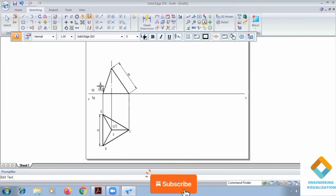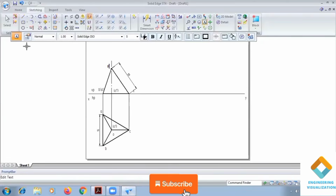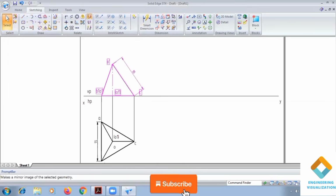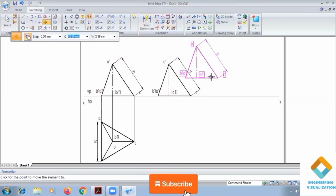So we are writing the front view notations: B dash visible, A dash not visible, O1 dash and O dash. Okay, next, in the second position it is nothing but the inclination with the base edge here. Now we'll select this front view and go to the move command. So here we are rotating, so we need to copy along the xy line and then rotate and give the angle.